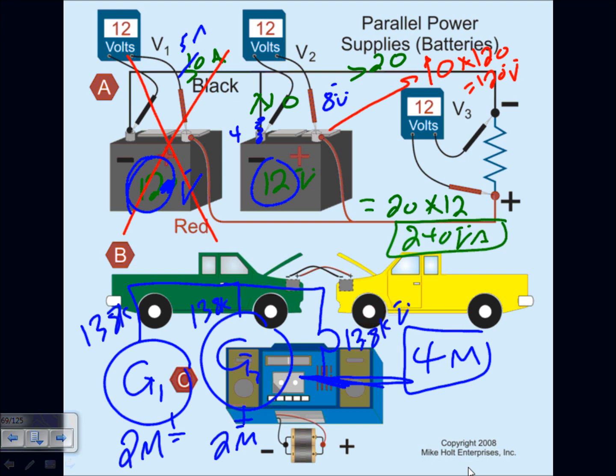Now, if you continue doing that, what's going to happen? You're going to burn your equipment. For a very short amount of time, they can handle a huge amount of current. But when the car is up and running and you turn on your radio and all this stuff, they're running on your battery, which is being charged by an alternator. If you start putting in a heater and your car plugged in and other things, your fuses will blow because you're at a stable condition. When you start, that's just a transient condition. To start the engine, you've got a huge amount of current, an inrush. Now it's running, everything is fine, and you're going to run loads on it. Any comments, guys? Good stuff.